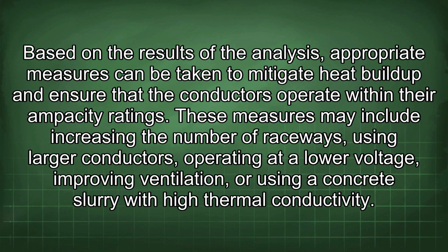Based on the results of the analysis, appropriate measures can be taken to mitigate heat buildup and ensure that the conductors operate within their ampacity ratings. These measures may include increasing the number of raceways, using larger conductors, operating at a lower voltage, improving ventilation, or using a concrete slurry with high thermal conductivity.